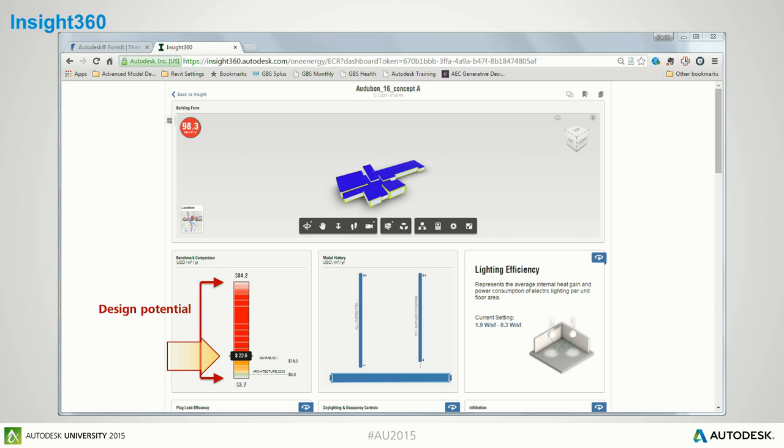In this early stage in the project where we don't have much of the building defined, you can see what we did is we built a form and we just pushed the button. We didn't define all the input and then run an energy analysis. We just pushed the button. So our results are very uncertain, and you probably can't see it here, but the range of our building performance is going to be from $4 to $84. So it's a huge range, and we're just admitting that you haven't given us a lot of information, so we're not sure yet, but we can still provide some useful workflows. On this chart, we've also got a couple of benchmarks, ASHRAE 90.1 and Architecture 2030, so you can see how you're doing compared to some typical benchmarks.